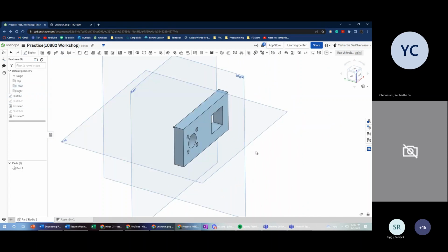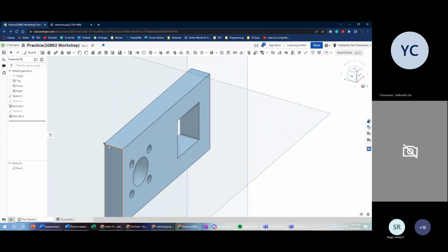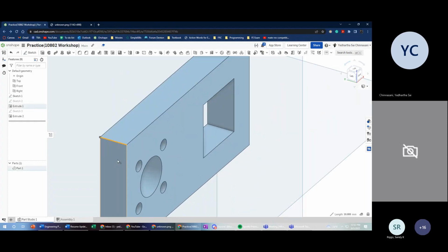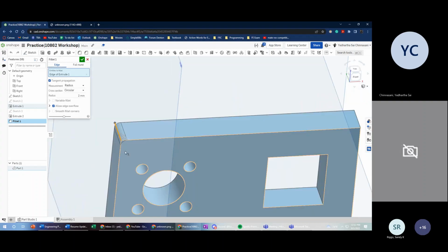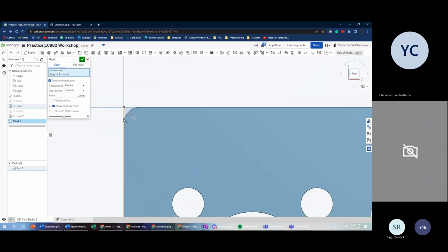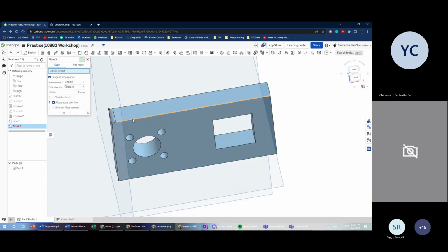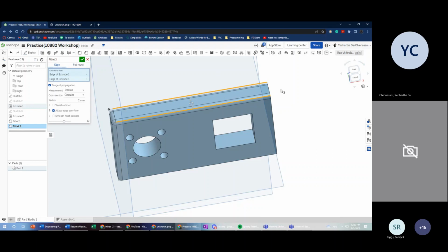Now I'm going to come over to what happens after you extrude. Let's say that you want your part to not have sharp edges, right? This is something that we do a lot in FTC because you can't have any, or it should be done. It's a good practice to be done everywhere. So whenever you have a sharp edge, what we do is called a fillet, and we edge it. It creates basically a circular face instead of a sharp face. So that's a fillet. You could do that to any corner. So like, let's say I do this corner, and this corner.